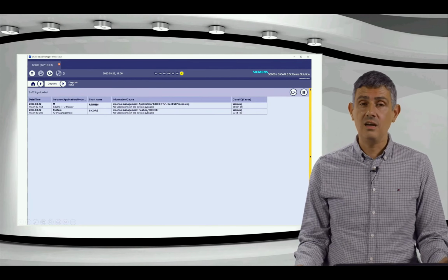Now, we will have to assign signals to this event list and alarm list. To be able to do that, we need to open them first. So we can just open both at the same time. How? I can just select both, and then I will use this Open Selected Objects button. Then the two objects have been opened in the middle. I can see that the event list total is actually selected here. So I will just jump to the Signals tab.